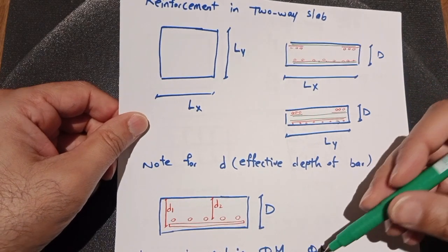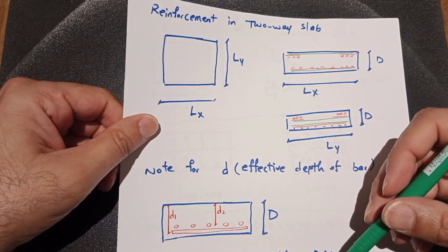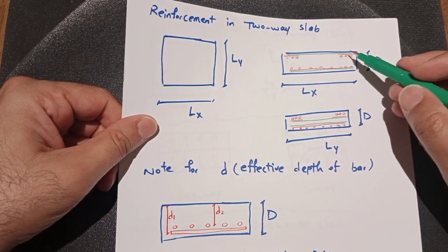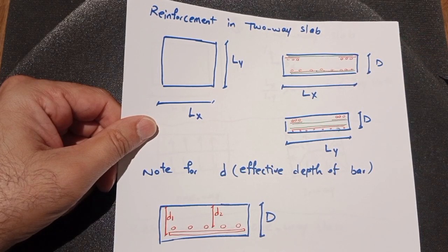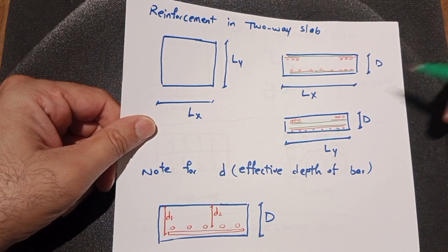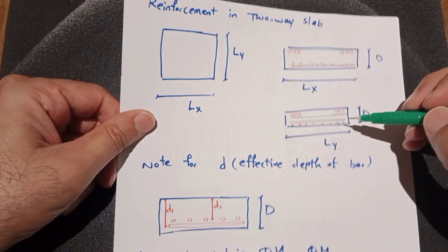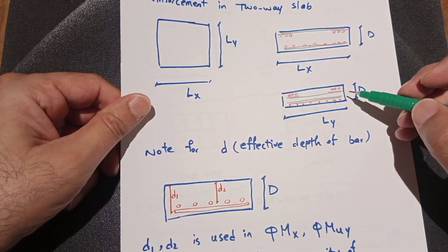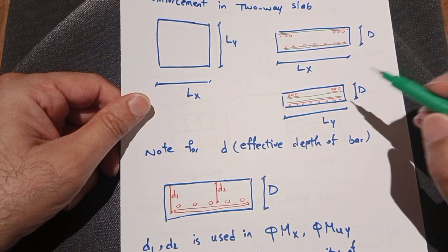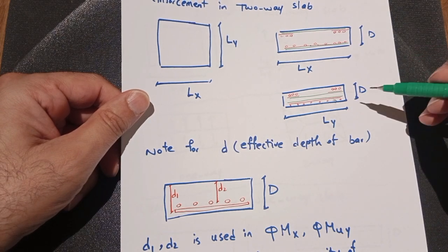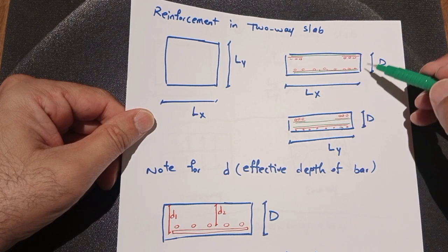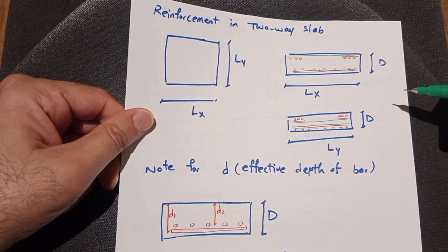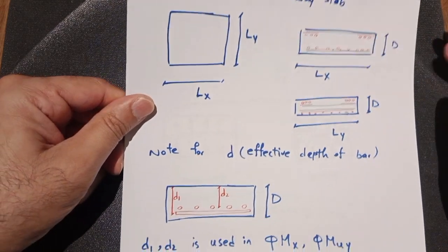Again, depending on the crack control reinforcement required, we will check it against the bars required in that direction for strength and deflection, and whichever is bigger, we put that. So the same here: if we consider crack control reinforcement, deflection control, and strength control, we will have top and bottom reinforcement in both directions.